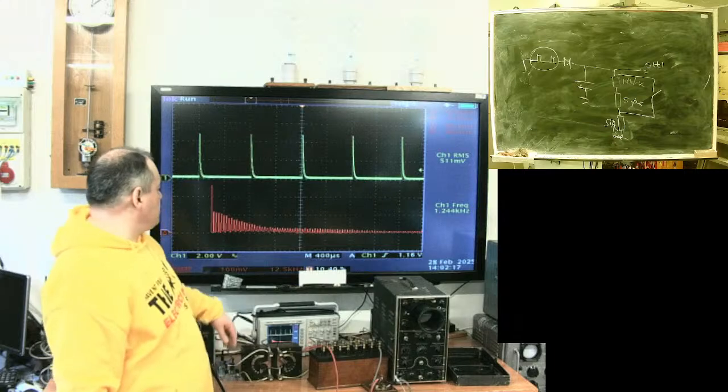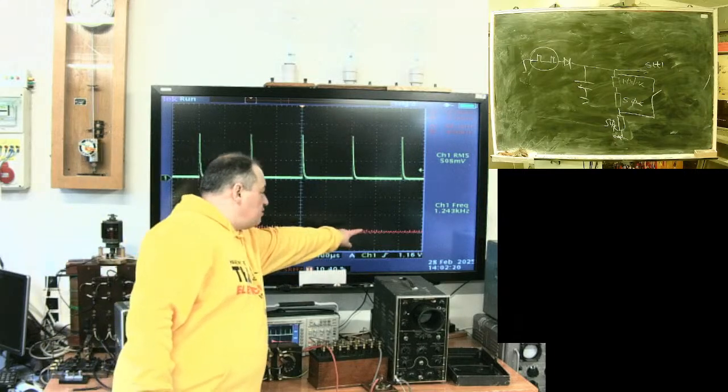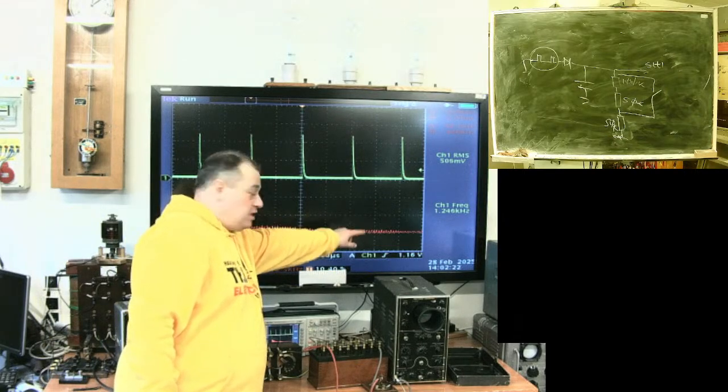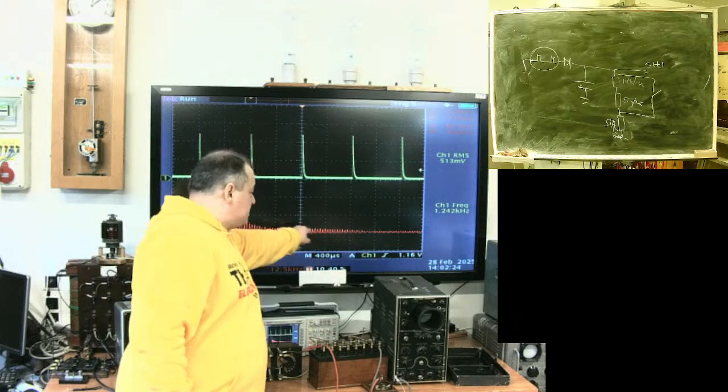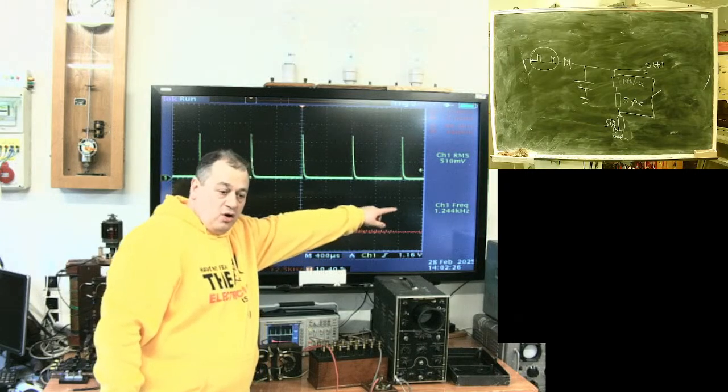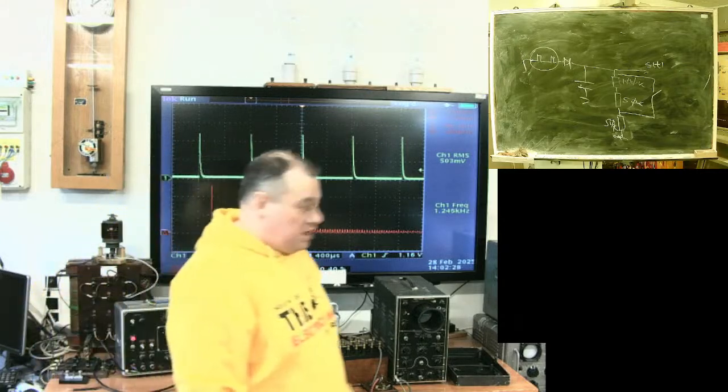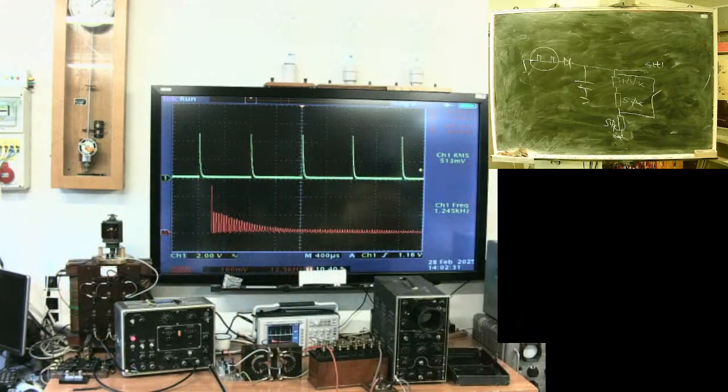With this rapid change, you see the tailing goals are relatively small, but they go on for long. This means that in case of such very fast changes, you will probably face an EMC problem, electromagnetic compatibility, because this high frequency component will interfere with radio broadcasting, TV, with your systems, digital brains, and so on.